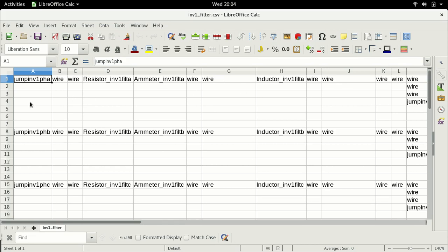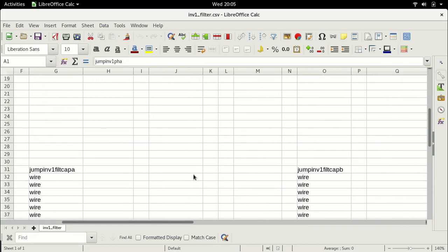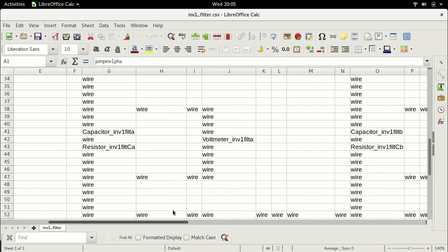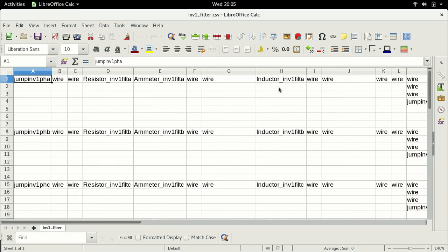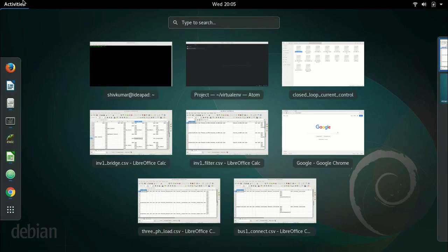As you change this inverter output voltage, you are changing the current, and that in turn results in this capacitor voltage changing. So the way we are going to do this control is, to regulate the capacitor voltage, which is the output voltage of the UPS, we need to first regulate the current output of the inverter. In this lecture I'm going to focus on how you can regulate the current through this inductor to some desired value, and in the next lecture I'll tell you how we can set this desired value according to the output voltage of the UPS. Anyway, let's get started with some simulations.